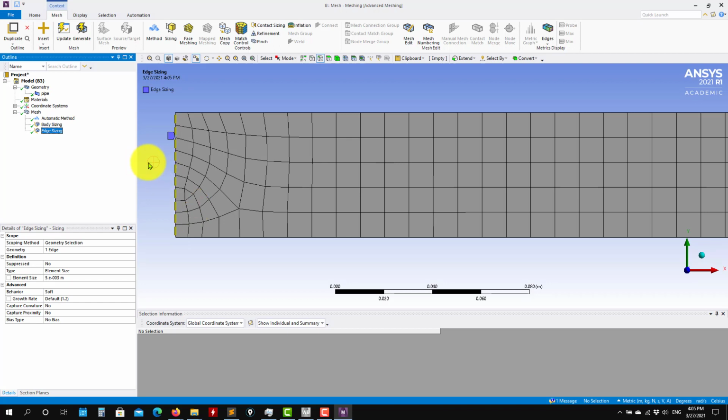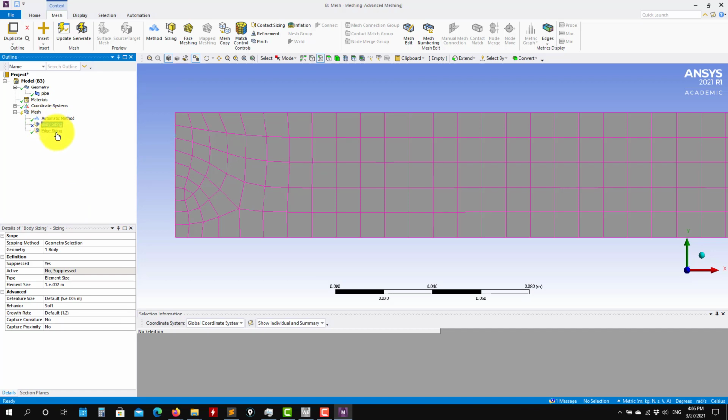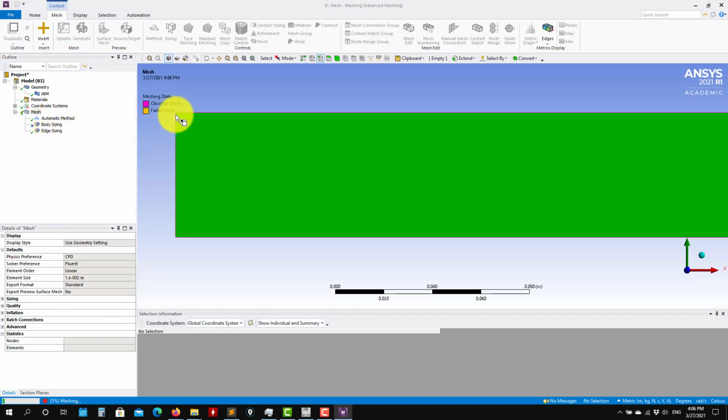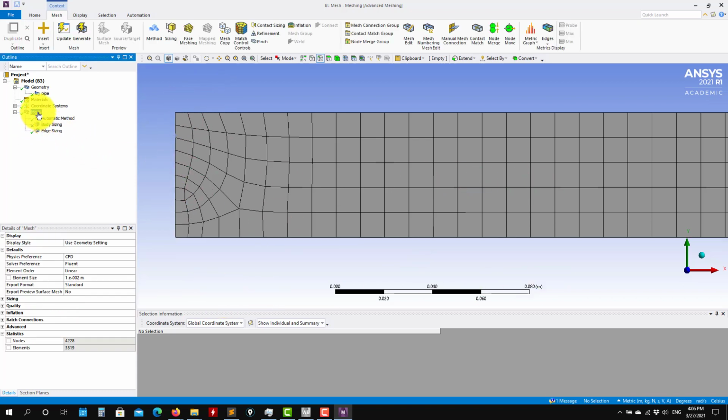A structured mesh, what it will do is that you define a dimension here, and everything will be propagated in the whole domain. But you need to force that kind of mesh. So let me suppress this here. You see here, suppress. I don't want to use that option. So again, as you generate, it will generate just using this edge size and the global sizing parameters. But if I want to propagate this size in the whole domain, there is another option.